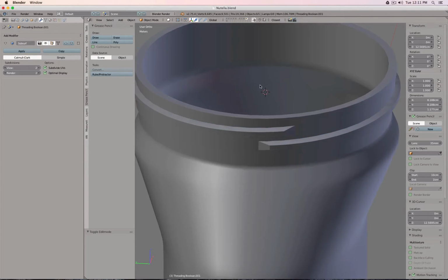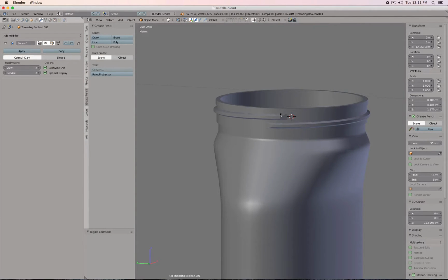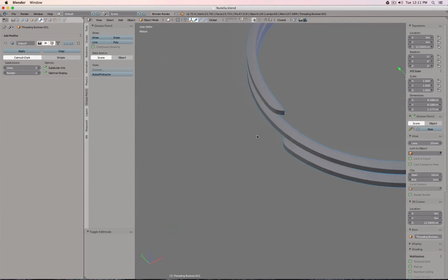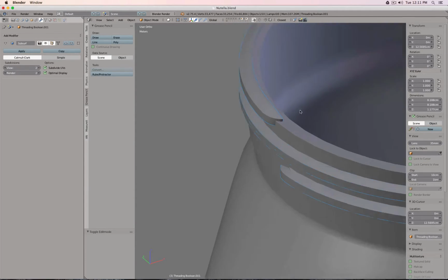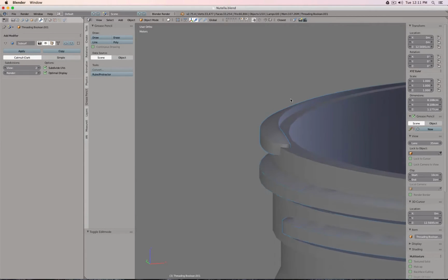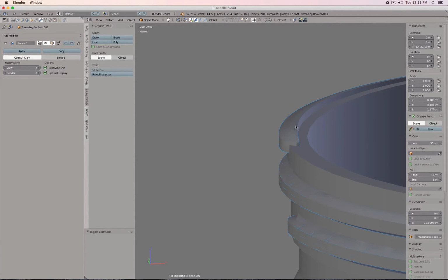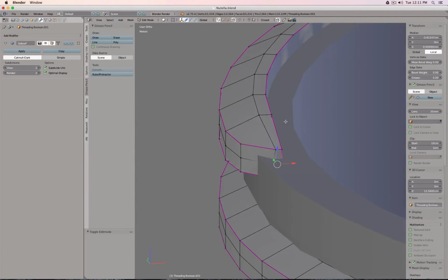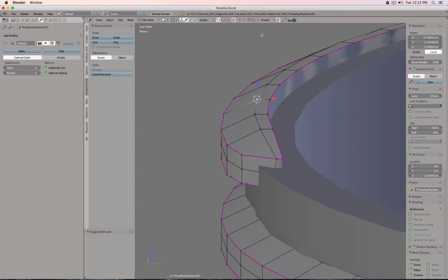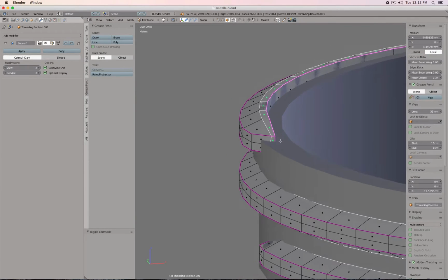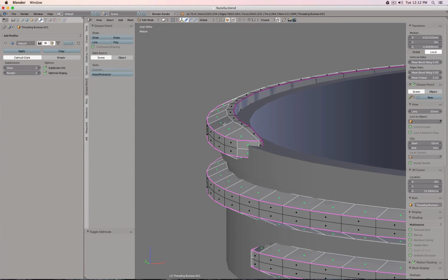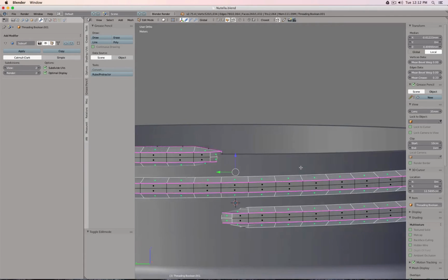Okay, so that's, for example, how we could quickly build kind of like a mechanical looking threading like this. Or, for example, then how to sculpt a threading. And you also see actually that from the beginning, I built this threading intersecting into the bottle, so I don't have to move the endpoints later. That's actually why you see there is this flat surface here, and that always is inside the bottle, and then this one intersects into the bottle a little bit.